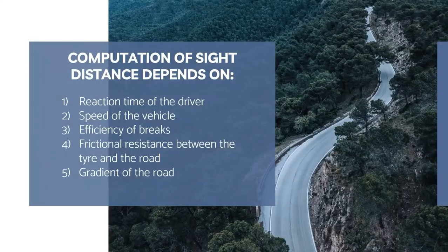The computation of the sight distance depends on the reaction time of the driver, speed of the vehicle, efficiency of brakes, frictional resistance between the tire and the road, and the gradient of the road.